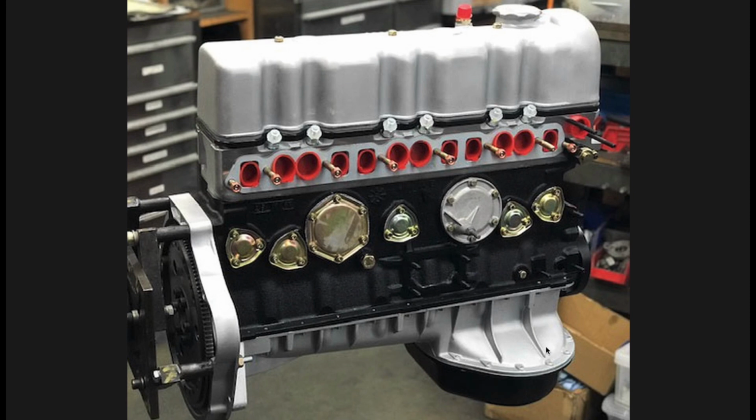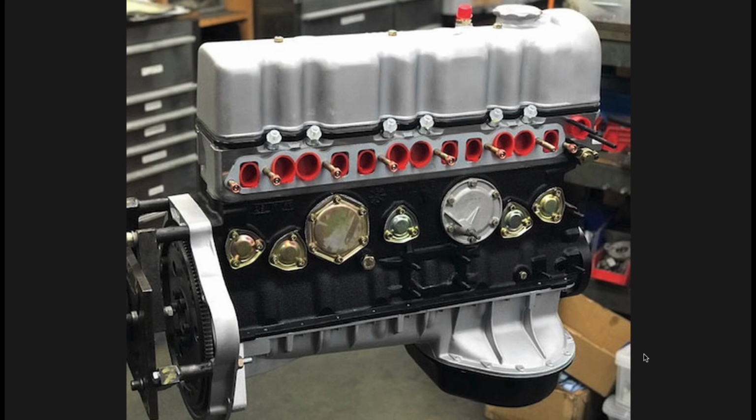And down here you would have an oil pan gasket, again to prevent oil from leaking out of the engine. This part is the flywheel, and this is what connects with your transmission. Now just two more things before we move on into the internals. I wanted to mention this part, and this is where your exhaust will come out of, as well as where the air gets sucked in for your combustion process. So you would have an exhaust or an intake manifold here.